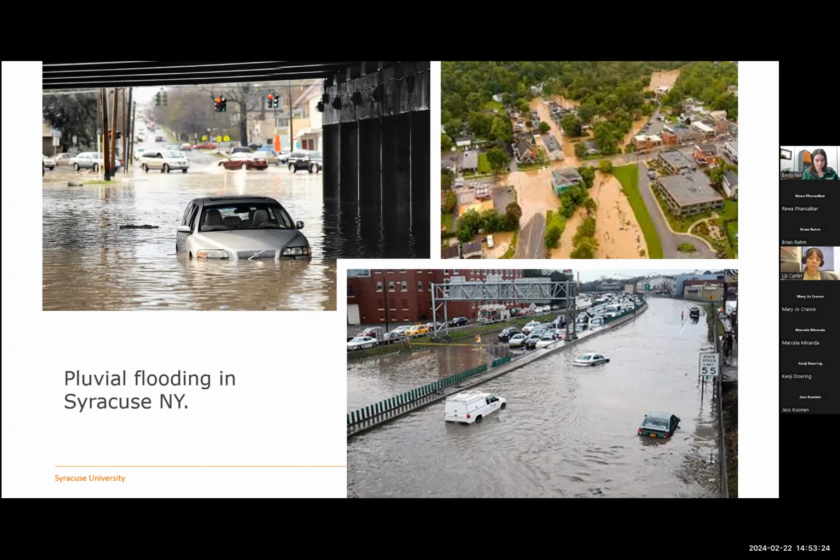So the main source of floodwaters for our urban pluvial flood events are backups of the municipal combined sewer overflow system. So our surface flooding occurs most often when our stormwater infrastructure is backed up, and therefore the combined stormwater and sewage effluent are essentially getting pumped into people's basements or percolating up through storm drains and then standing stagnant on the ground. So these aren't just floodwaters. These are sources of contamination and potentially sources of